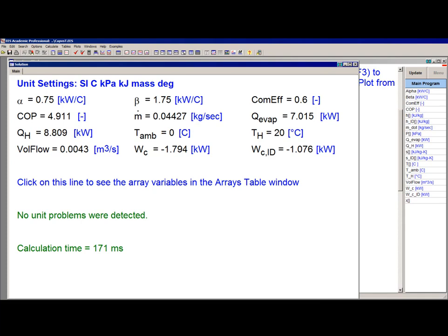However, if at some point you have an array that has 5,000 entries and later you reduce its size to only 500 entries, you have to remember that EASE is going to retain in memory the original 5,000 variables. It's not going to purge any of them even as you've resized the array. So 4,500 of these variables aren't being used. And this really becomes an issue when you're working with arrays.